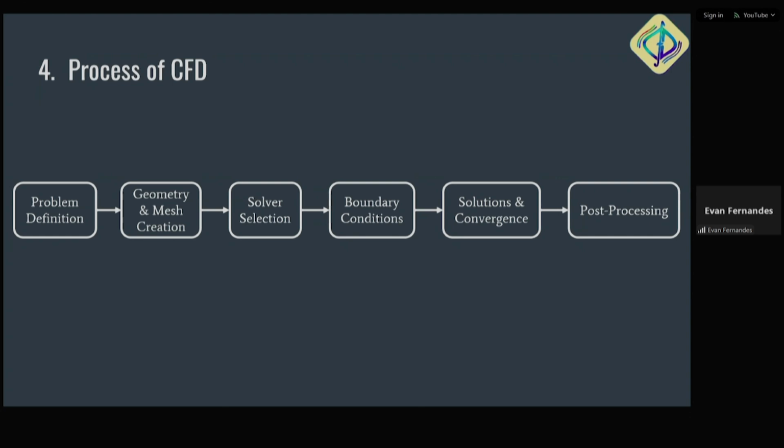One good thing about OpenFOAM is you can use Python or any other software to write your custom code to compute something once your simulation is done. Take the airfoil case. If I have that airfoil and through the simulation I am getting some forces, say the pressure and viscous forces, I can write a custom code in Python to find the frequency of the vortex shedding happening behind the airfoil. Along with that, I can also find the coefficient of lift and drag all at once using the post-processing utilities.